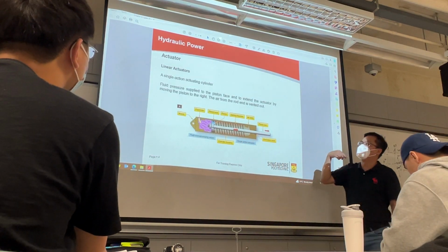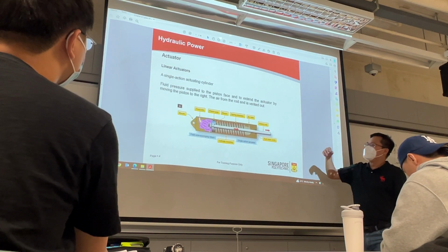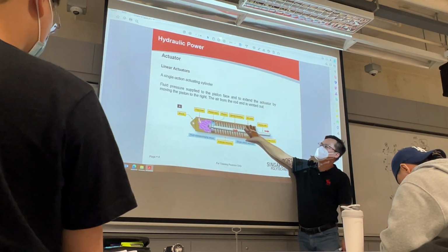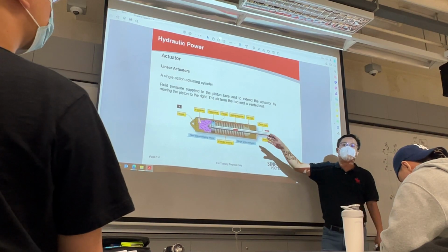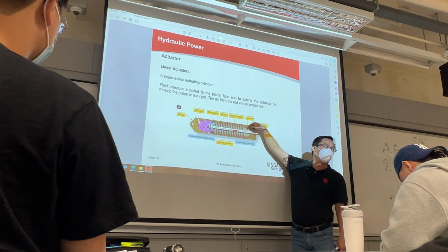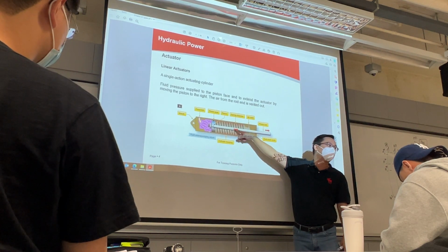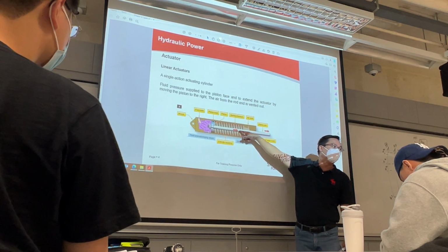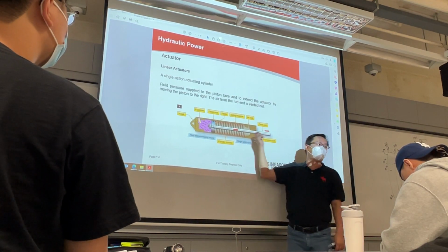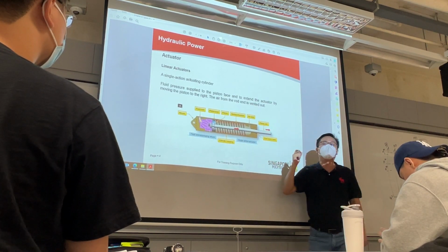Now in my time, in my work, after they service this actuator, before they send it to the warehouse for you to use, they will cap this area so that no foreign objects or animals or insects will go inside and build their own family. Because in that case, if I've installed it on the aircraft, then they will restrict the extension stroke. So we need to do that.